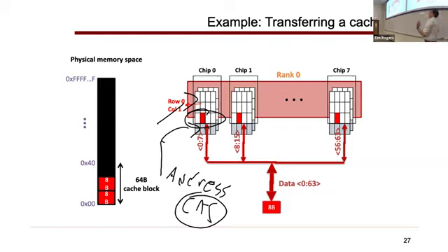It really only matters if you don't have enough parallelism to initiate another cache block access, which usually isn't true with prefetchers and multi-threaded systems. And even an out of order processor is going to have like 7-8 loads or more from each individual thread. So you usually have enough blocks in demand that you can soak up the channels without having to spray each cache line across. But that's a good question.